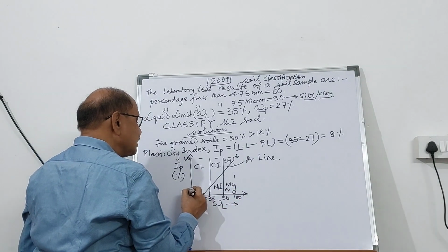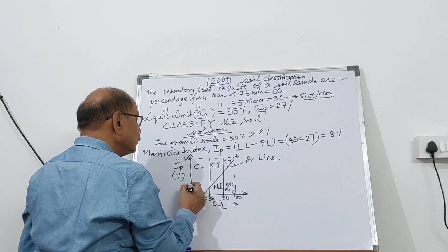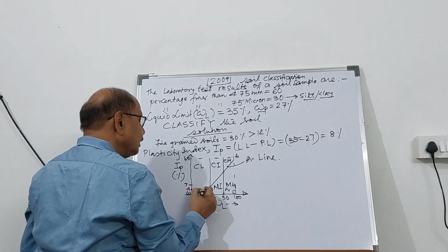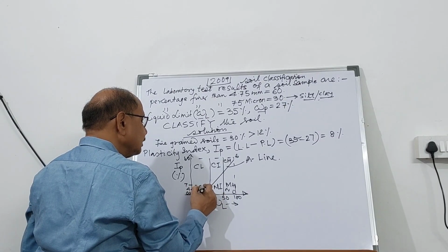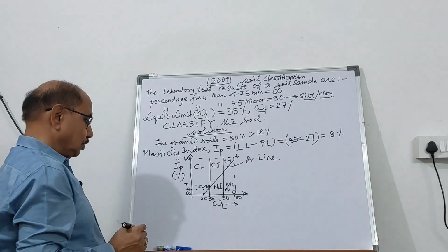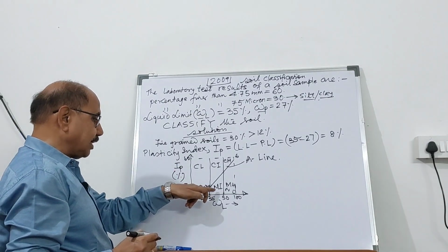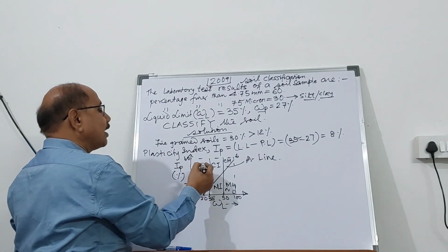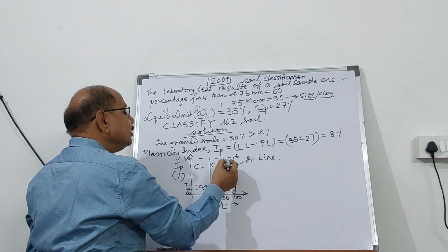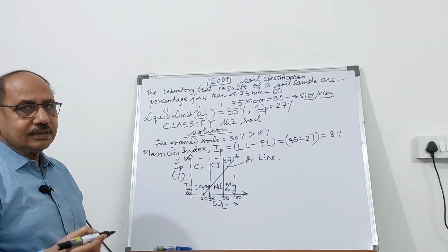And between 4 and 7 IP, it is a dual combination known as CL-ML, where C stands for clay, M stands for silt, L stands for low plasticity, I intermediate plasticity, H high plasticity.